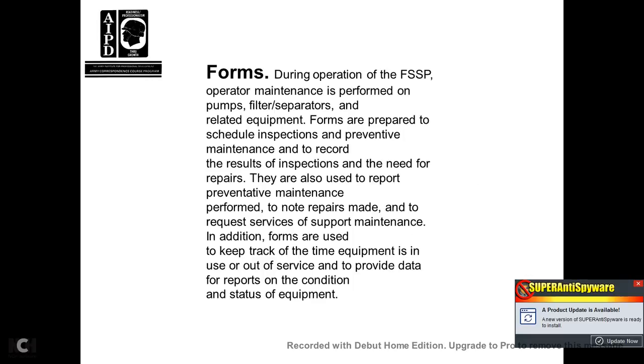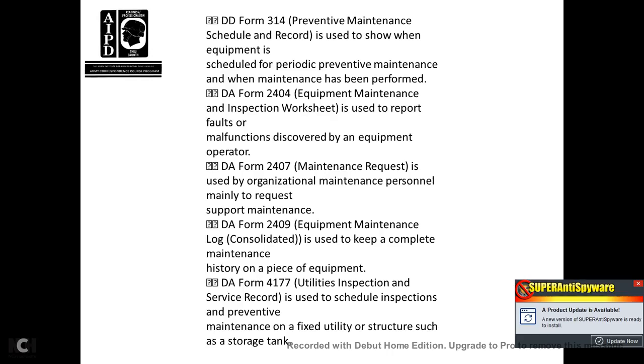Forms. During operation of the fuel system supply point, operator maintenance is performed on the pump filter separator and related equipment. Forms are prepared to schedule inspections and preventive maintenance, and are used to record the results of inspections and the need for repair. They also report preventive maintenance performed and repairs made, and request support maintenance. Additional forms are used to keep track of the equipment and its use, and provide data reports on the condition and status of equipment.